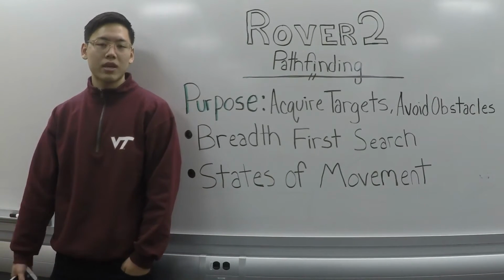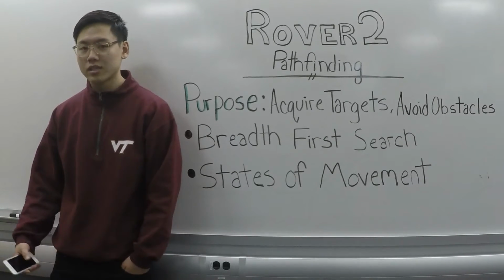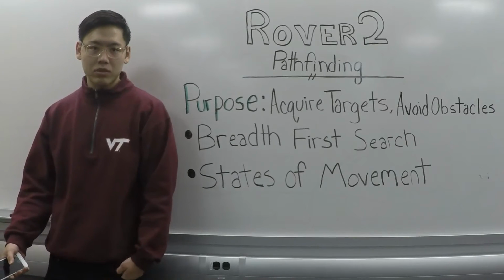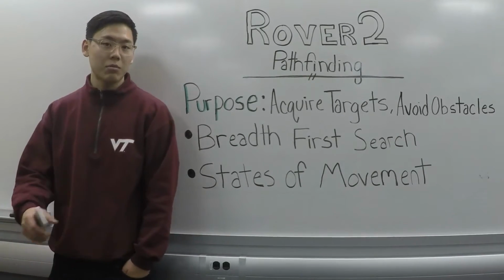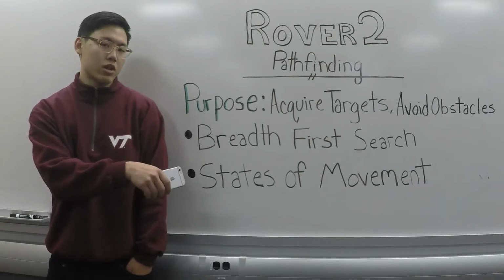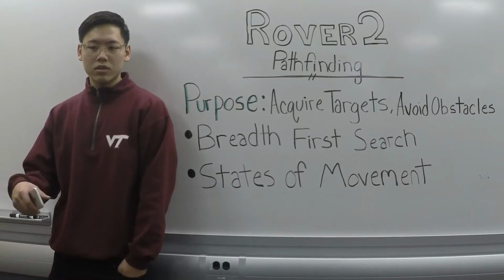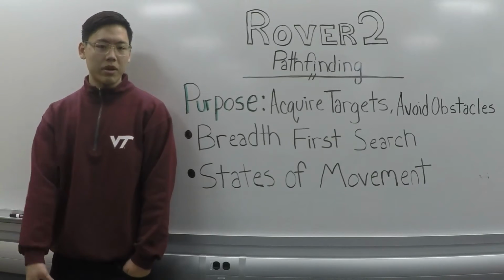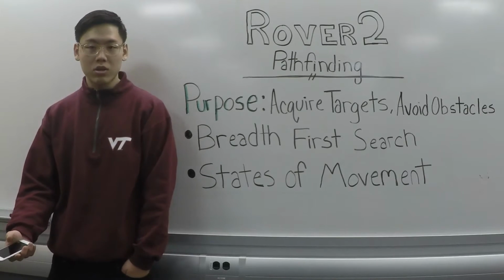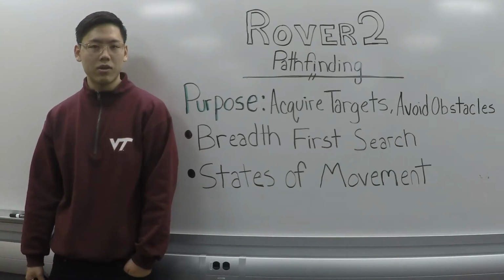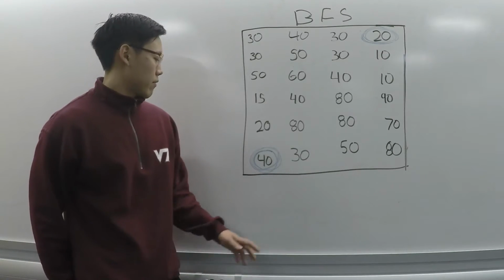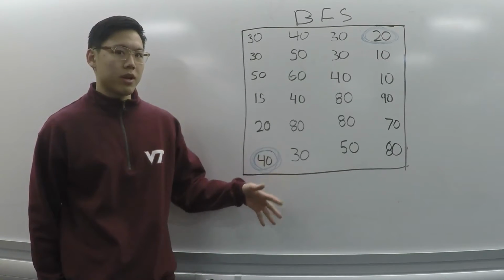In a given map that gets transferred in the map exchange state, which we talked about, I use that map to identify the closest target to me and I move to that target while avoiding obstacles. I do this by doing a breadth first search algorithm. I first looked into an algorithm called A* and I implemented my own based on the A* algorithm. The difference between mine and A* is simply that I take the difficulty value and add it to the weight. As mentioned before, regarding my breadth first search, I'll briefly explain how it works.